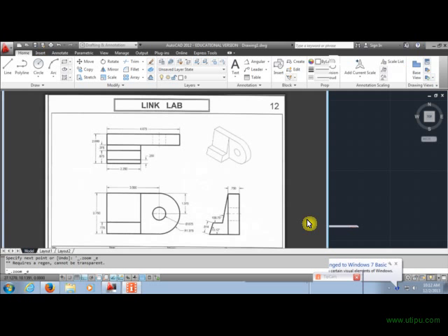Okay, so there I have my object line, and I can now use the ellipse command and center it right on this spot here, which I know is the center of the big circle. So I will tell it isocircle again, and it says where's the center. I click right here. What's the radius? So what's the radius of that really big circle there for the arc? 1.375. So, and I have created my arc section.